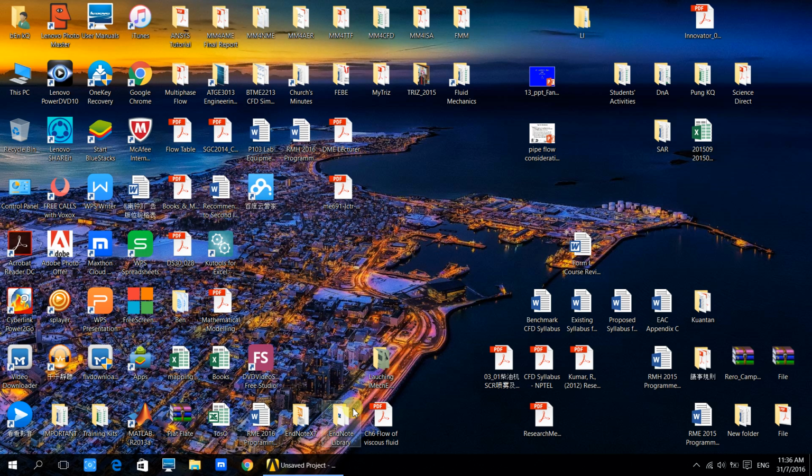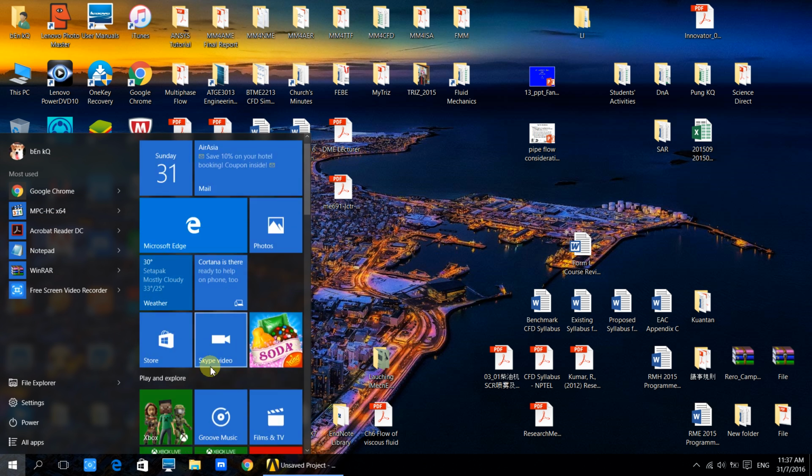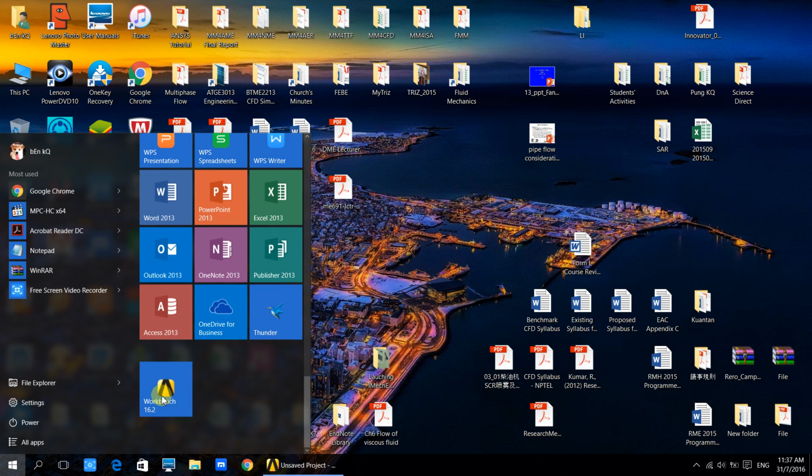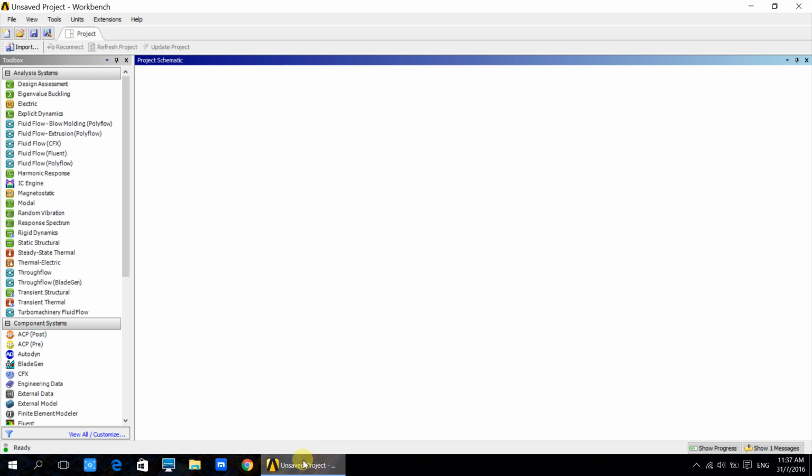Hi, in this video I will show you how to use ANSYS DesignModeler to create a 2D model. At first, go to Launch Workbench on your desktop. Either version will do. After launching, most probably you will get this interface. Let's drag this FLUENT from the analysis system, put it onto this workspace, and give whatever name you like, for example A, B and C.